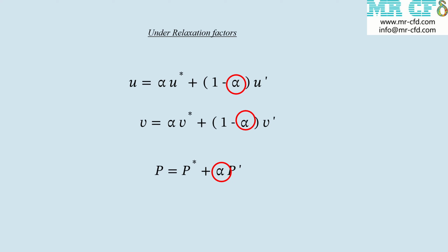If we have trained or established a better initial condition, we can opt for higher under-relaxation factors. Conversely, if our initial condition is far from the expected result, lower under-relaxation factors are necessary. This is because, in the initial iterations, corrections calculated by the algorithms might deviate significantly from the physical reality. As the solution becomes more accurate and assumptions are reduced, for instance from SIMPLE to SIMPLEC, higher under-relaxation factors can be used. This is due to these algorithms providing more accurate pressure corrections.